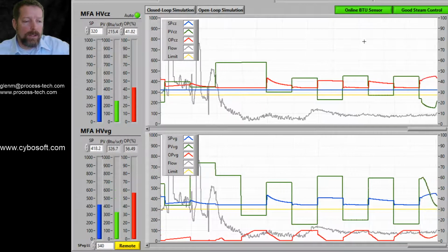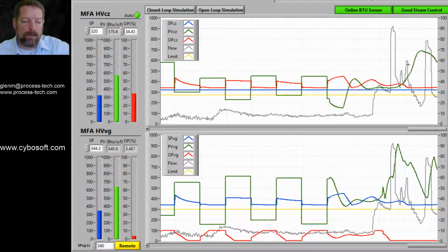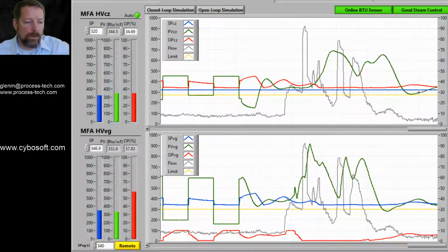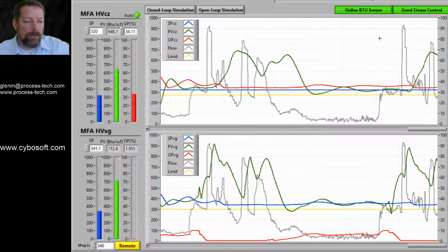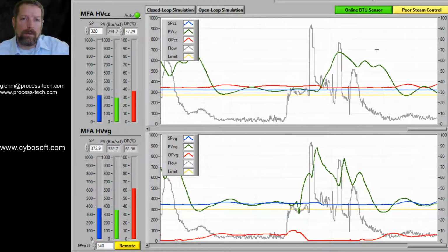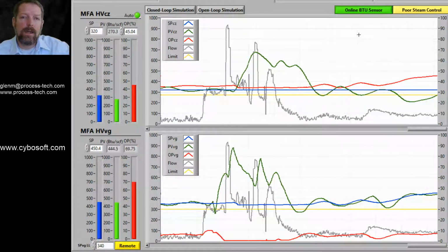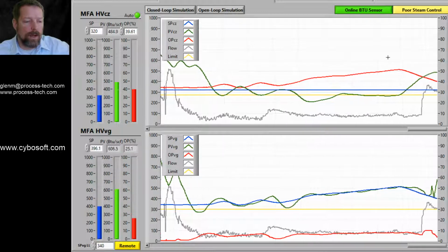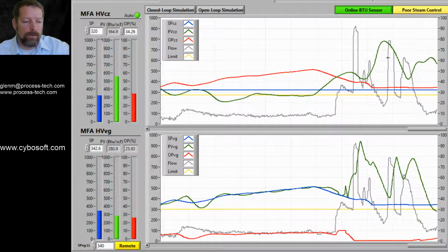So switching that back off, you'll see the square wave that is the time that it takes for a gas chromatograph to get net heating value has returned to a much more fluid flow rate, or rather fluid measurement. If you don't have sufficient steam control, and again this example is assuming the customer has steam, we are aware that many of our customers have air assist, and we can talk about that in detail at the training class in April 3rd. But if you have poor steam control, you can see how the steam control would challenge the control system to achieve set point.